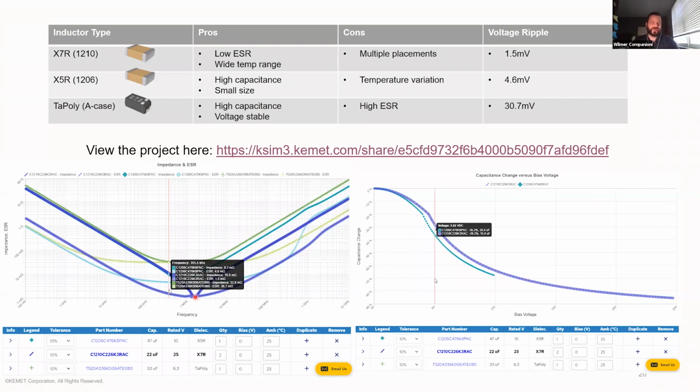It'll be hard to say that we have anything that just goes 1206, this is the ESL, 0603, this is the ESL, because the actual layer count and structure of how these multi-layer ceramic capacitor options are built up also have an impact on the ESL.